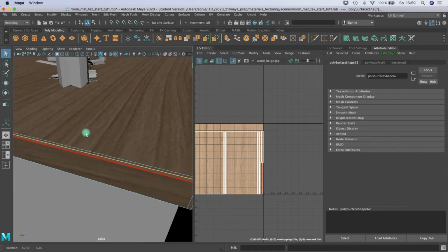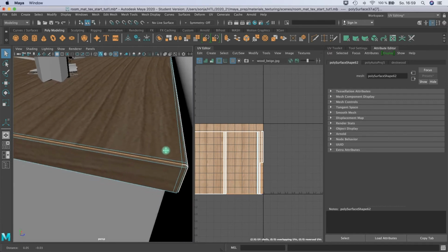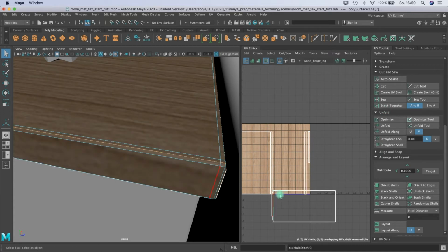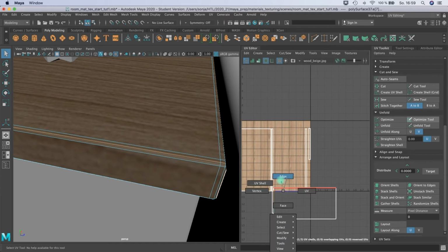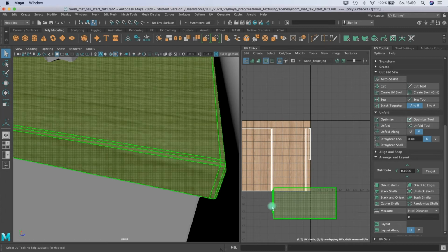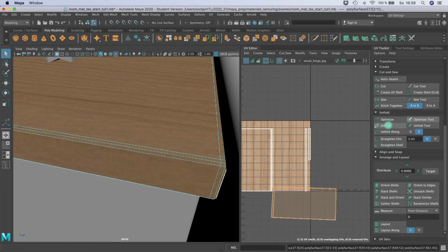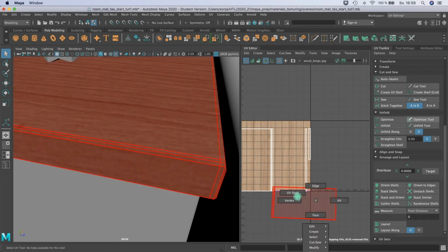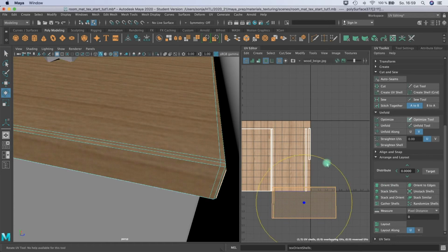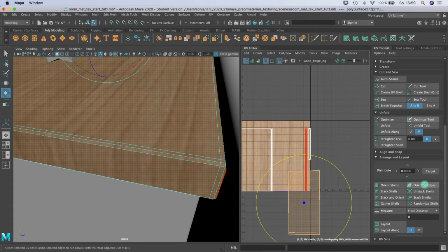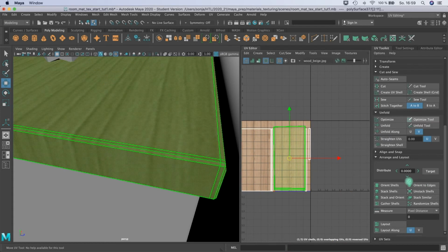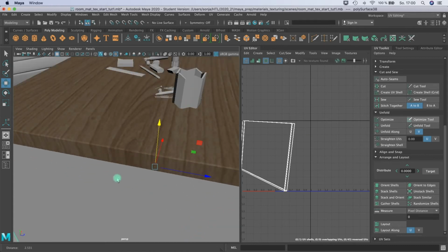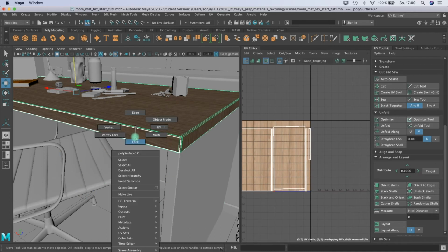You could also leave it that way, but of course when I want to get it perfectly here, I switch on my UV toolkit again and say stitch together, and now it rotated. When this happens, and also the sizing is a little bit different, you select the shell again and say unfold again, and then the size will adjust. And I take the shell, orient it here perfectly, or maybe orient on edges. Let's see what happens. Oh, there's nothing. Good. We just oriented it, and you see now the texture is flowing perfectly over the edge.